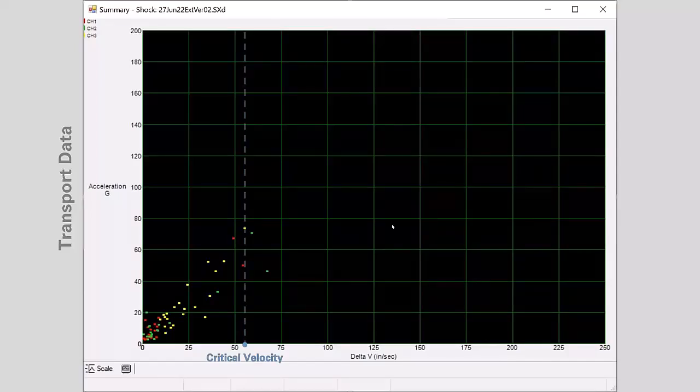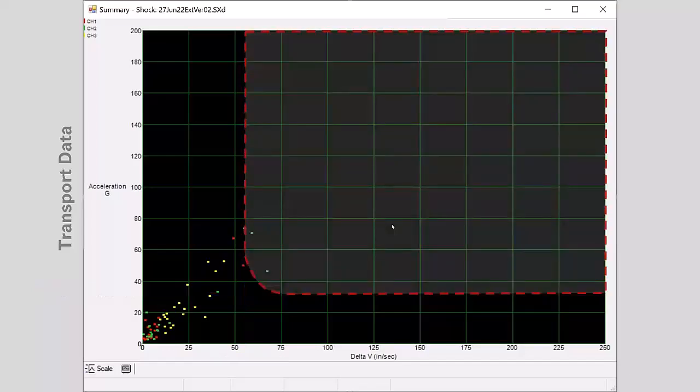Most people might look at this when you get it back and say, I don't understand what I'm looking at. Well, think of it as a way to assess, if you know the damage boundary data, which I did for my spring mass system with the washer on it: if I sent that out into the supply chain and it was exposed to all these events that the recorder recorded, would any of them pose potential damage to that widget?